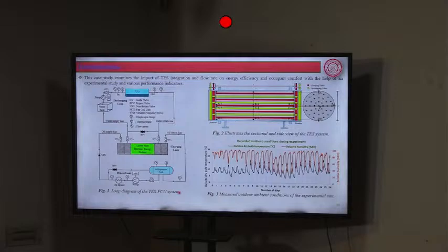The next one is a very big system where we had a poly generation at IIT Delhi. Visit the facility. We have a thermal battery which is utilized for space heating, probe drying, and cooking, and all those poly generation activities are being backed up utilizing the thermal battery. That thermal battery is actually a combination of solar salt and nitrates and nitrites of sodium.